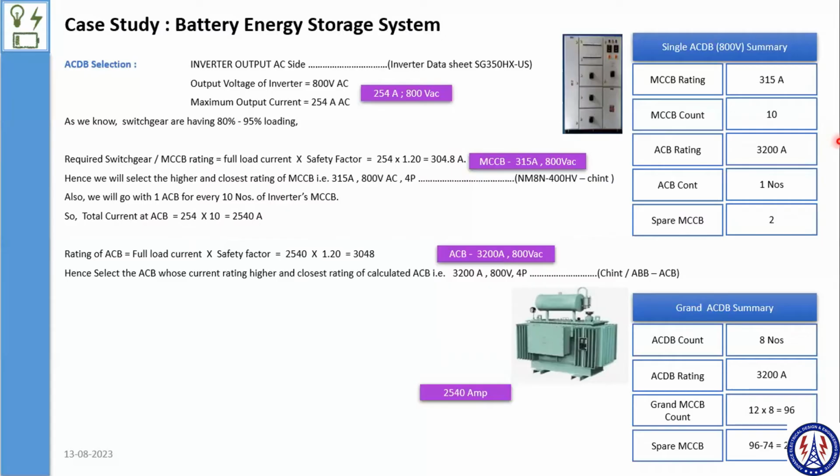But after that, whether that particular ampere ACB is available or not, you need to check, right? If you club 20 and there is no ACB available, then you need to recalculate. And because of that recalculation, you will realize that 10 would be the good fit.